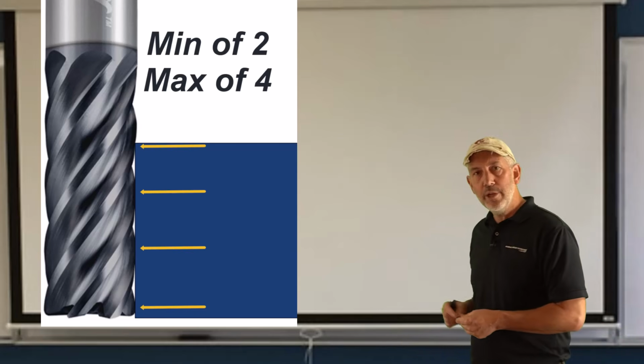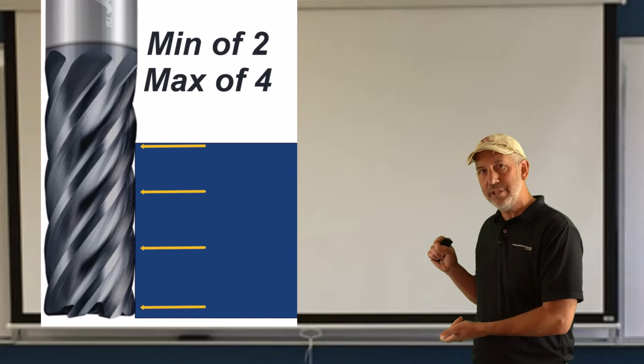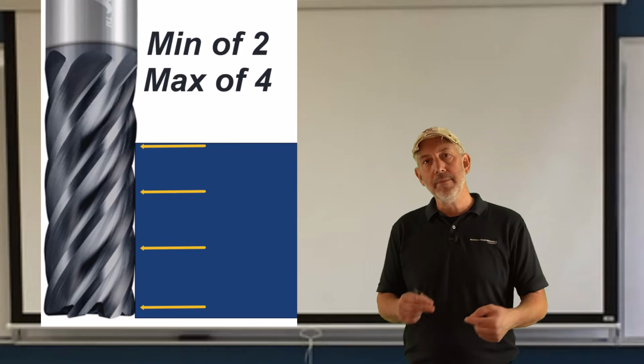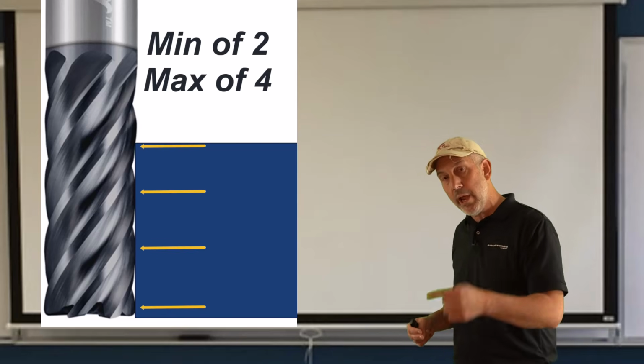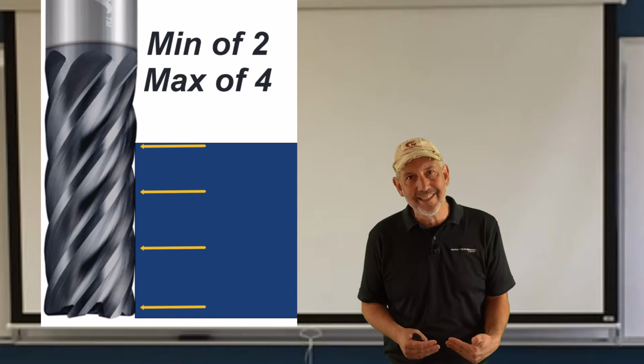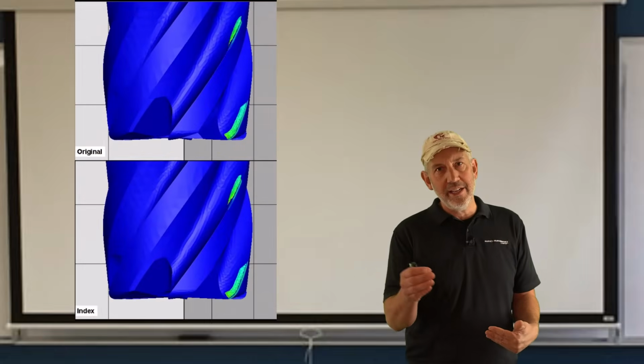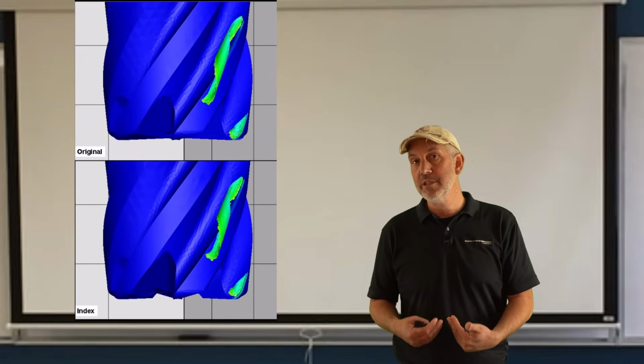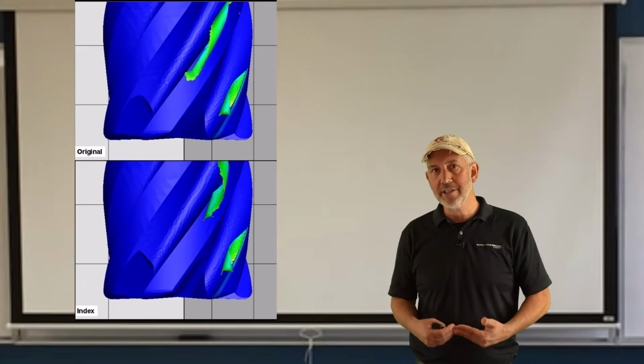So what we want to do is, by taking a longer axial depth of cut, lighter radial, we can maximize how many flutes are in cut. This way, when one flute exits the material, there's another flute or 2 flutes that are in that material, so you don't get spring back. That tool is not springing back.